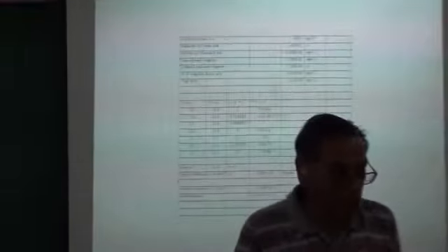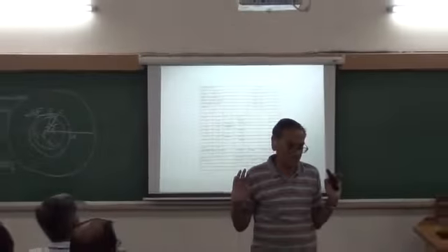The rigidity modulus is 4 pi times the moment of inertia divided by 4th power of the radius into the slope. So you measure the slope, you know all other quantities, calculate the moment of inertia. And I get a value 4.05 times 10 to the power of 10 pascals, that is 40 GPa. The Young's modulus will be 100 GPa. So the rigidity modulus is 1 by 2.5 times the Young's modulus.